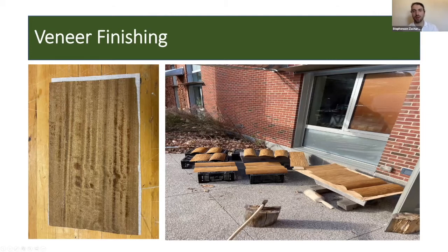So when we started processing these lamps, one of the first things we had to do was to process the veneer, since it took one of the longest out of all the steps. So in order to do that, what we did first was we ironed on both backings of the fabric interface in order to give it that reinforcement that I discussed earlier. And then we hit it with the oil-based poly and let them dry in the sun for about 4 hours before bringing them back inside to give it another coat, and then allowed it to dry again overnight before giving it just a quick rub over with some sandpaper just to get off any blemishes on the outer surface of it.